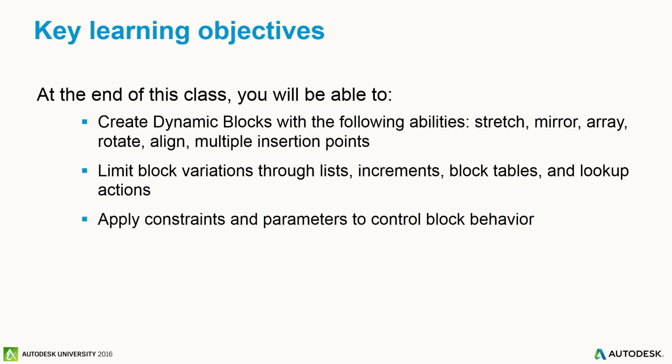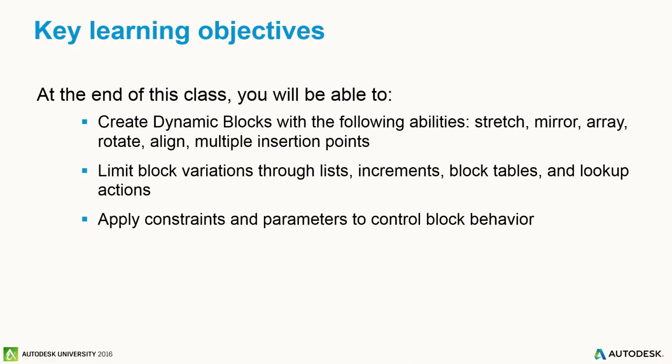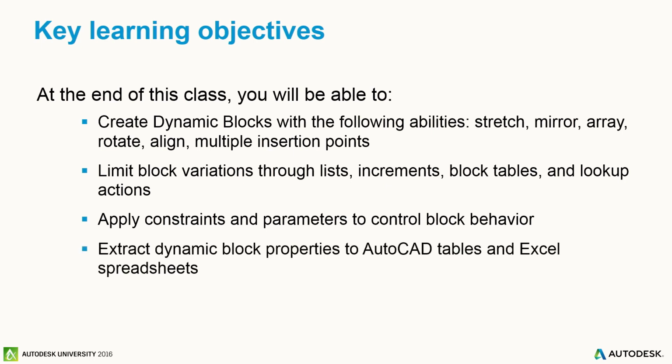And then we'll take a look at how we can use constraints as well. How many of you have used parameters or constraints in AutoCAD? So a little less than half. Okay, so for some of you, this might be the first time you see parameters. I'll actually go through the parameters kind of quickly since that's not really the focus of this class. But then we'll go ahead and see how we can use those in dynamic blocks.